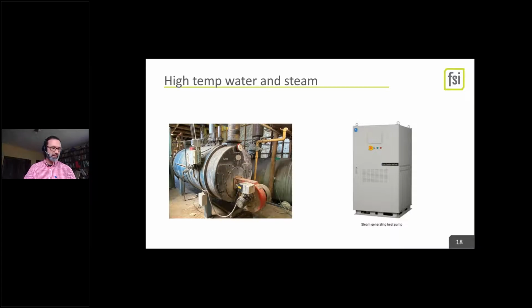And even a cascading loop heat pump probably won't get there. And then of course steam, 15 psi steam, 230 some degrees or higher, isn't going to get there with a heat pump on its own. You can do electric resistance. Your energy will cost 2.5 or 3 times more and won't really meet the provisions of the code that require a heat pump.